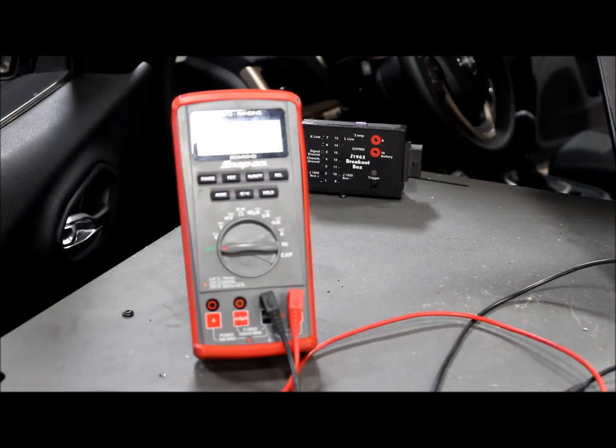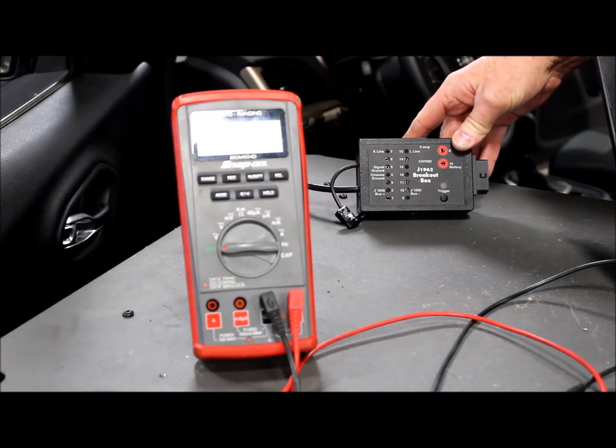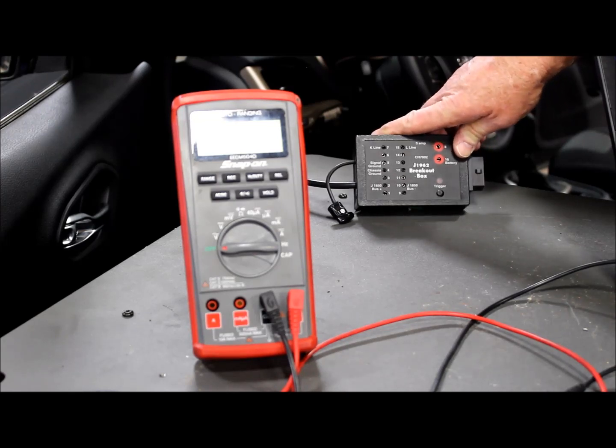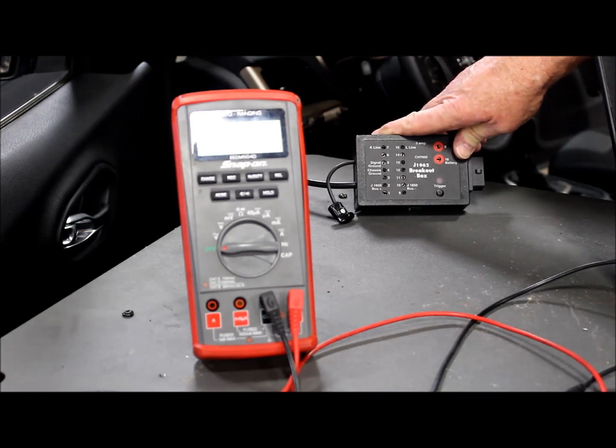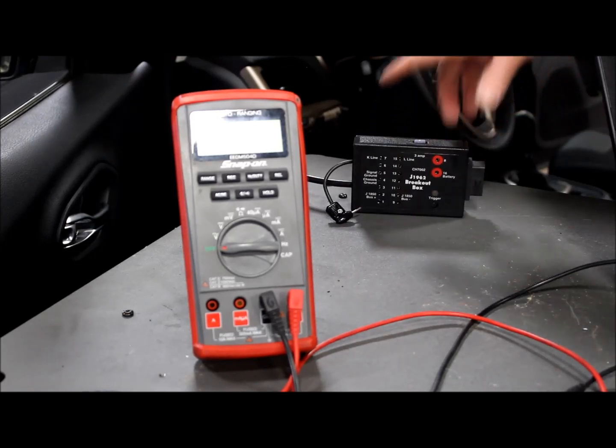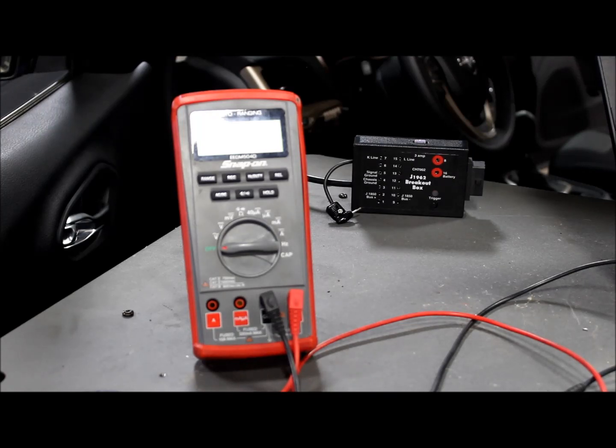I've connected a breakout box to the data link connector, and what that does is allows us to access the pins of the data link connector and therefore the different circuits in the network without actually jamming meter probes into the data link connector itself. So I'm going to use this breakout box to do a couple of things. Right now I have the battery disconnected, and I've looked up the specs for this network, and what it tells me is total resistance of CAN networks can be measured with the battery disconnected. The average resistance is approximately 60 ohms.